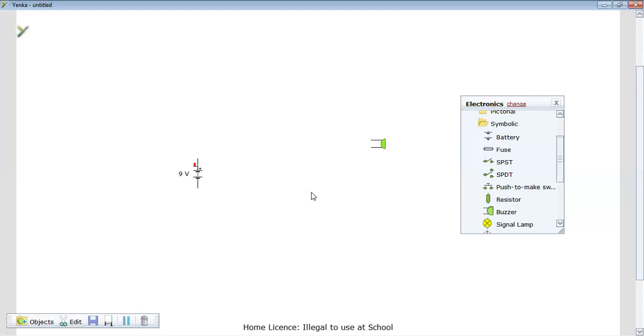Now, if you remember when we did our electronics lesson, we looked at lots of these symbols. So we're going to start off by getting one of our basic ones here. You'll notice there's two resistors on there. So down here, under our basic components, we have resistors. So I'm going to get the first one in, and it's about positioned there on the PowerPoint. First of all, I've got 680 ohms there, but the one on the PowerPoint, resistor 1, is 10K. So I'm just going to change that to 10,000. And as it does that, it changes it to 10K ohms.